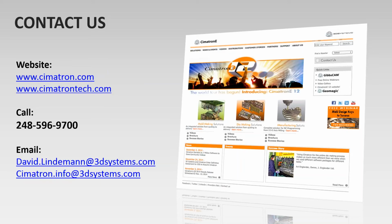As far as the finishing, again this goes off my own research, they're claiming that printing gives you 99.9% density. So whatever porosity is there is considered microscopic, and they're claiming they can get a B2 finish by polishing, which typically would be good enough. If you're looking at something that requires better than that, like maybe an A2 finish for a lens, then it becomes a factor you have to consider. As far as practicality, I'm not sure. I haven't dealt with anyone yet who is printing different materials in the same core, although it certainly is intriguing to think about, isn't it?